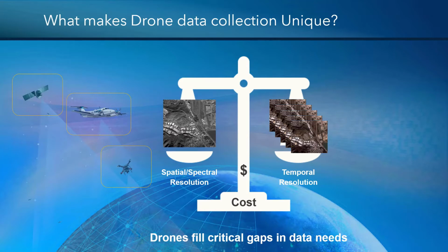Aerial photography is also good because we can get good resolution, 5 centimetre resolution imagery, and we can get that on regular flyovers, so half yearly, yearly sort of flyovers. The issue with aerial photography though is that it is expensive to run, and so generally we fly very large areas. So drones though, they fit in that niche area where we want high temporal resolution, so I can fly every day, every week if I require, and they give me a really good spatial resolution as well.